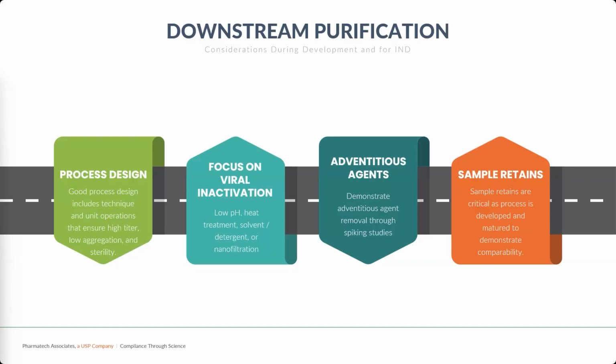As we've talked quite a bit about now, there's a focus on contamination, particularly in biosimilars. One has to show that the product that comes out is as close as possible to the original drug product that you're trying to create. And as we mentioned before, the viral inactivation processes and procedures you put in should be planned in advance and well characterized. Fortunately, there are a great many examples of bioprocesses and best practices available that one can leverage. Finally, it's adventitious agents, right? So how do those agents get removed? What is the process by which they're being removed, and how do you characterize and qualify those?